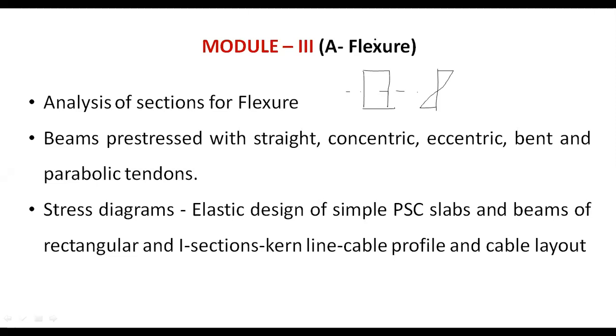So in this way, we are going to draw the stress diagrams of the pre-stressing elements like pre-tension and post-tension elements. Okay. So here we are going to treat the member in the elastic mode. So here the elastic designing of simple pre-stressed slabs, beams, and different kinds of sections like rectangular sections, I sections, right? And what is the way of cable profiling towards bending, and what is the layout of the cable? Cable in the sense the profiling cable. Cable profiling, right? And what is the cable layout? So these are the topics which are going to be discussed in the lecture, right?